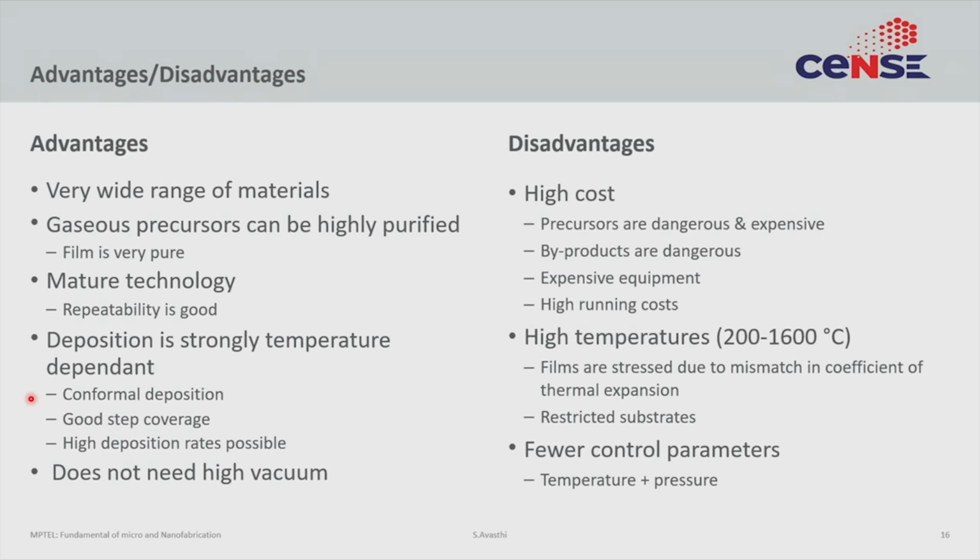The other disadvantage is that high quality CVD, especially epitaxial CVD, often requires high temperatures. Now, high is a relative word, but typically for high quality silicon CVD, you need temperatures in excess of, let us say, 700–800 degrees C. This has certain consequences on cost, which we have discussed, but there are also consequences on stress that develops in